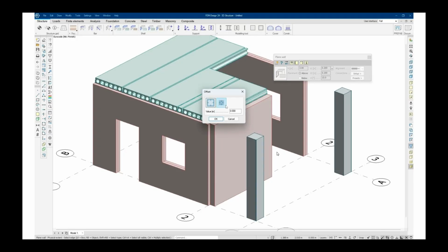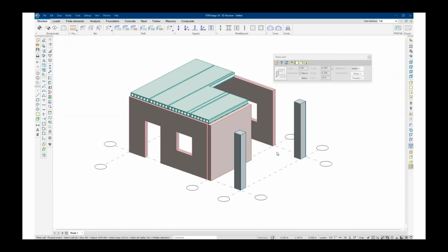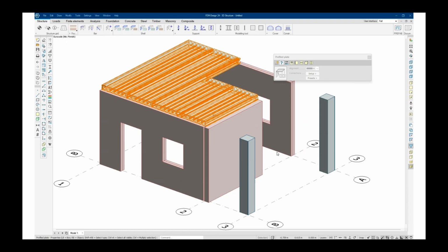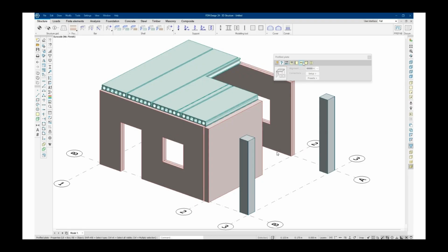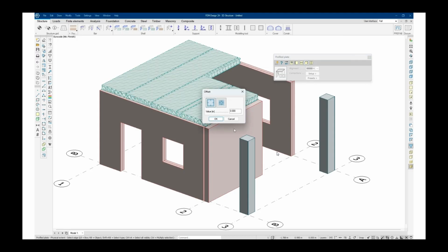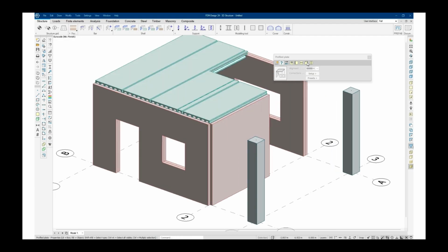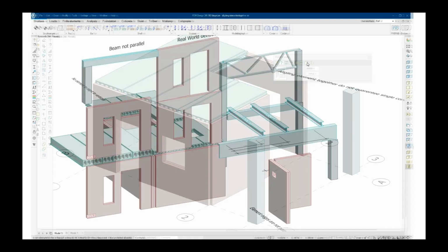Then the final tool is called physical extend. You can make elements bigger in the physical model, but in the finite element model they remain in the original size. Now you see the corner detail is correct, and it can be set in any model, and our finite element model will still be intact. It's this cube button here that sets the extent, whether it shrinks or gets bigger or smaller, but still the midline model is there. The finite element model is the original.